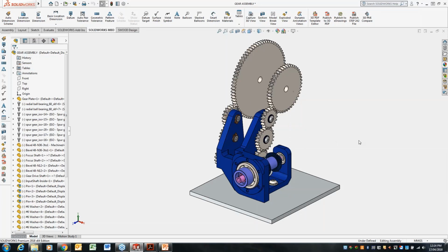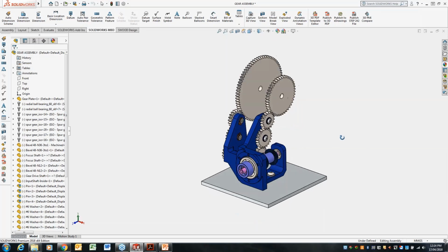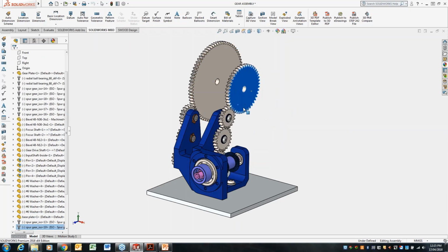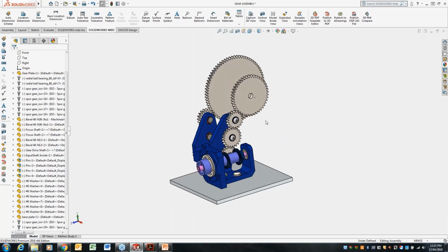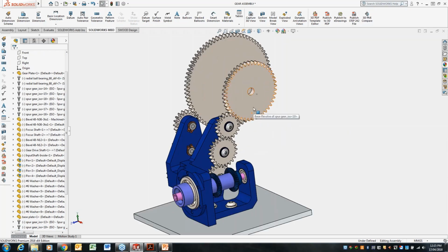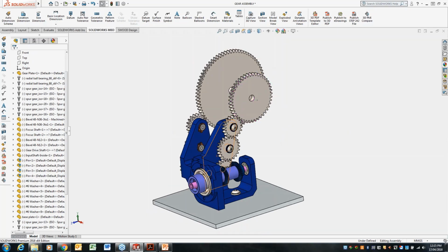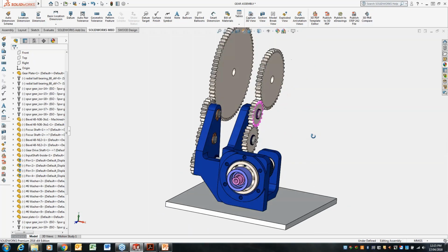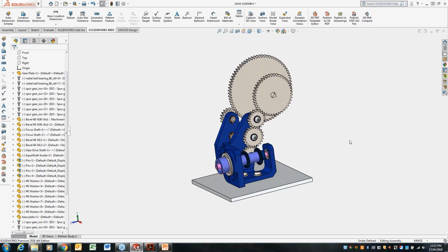We're going to use this assembly here that I have. This is for an underwater camera system, where the gears are meshed together for basically the pan and zoom actions for the underwater camera, and they need to be on a close tolerance with precise fits so that they can avoid water ingress. So the main feature is about manufacturing these holes for this gear plate here, which has to make sure that all the geometric tolerances are well oriented towards making this assembly run successfully.